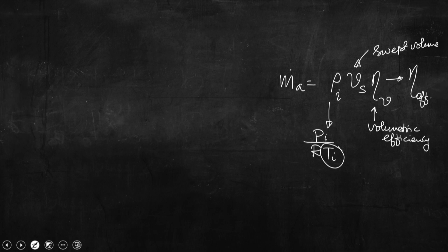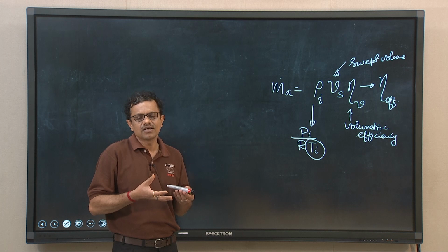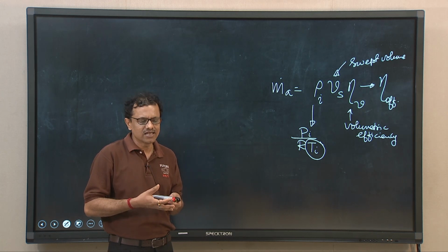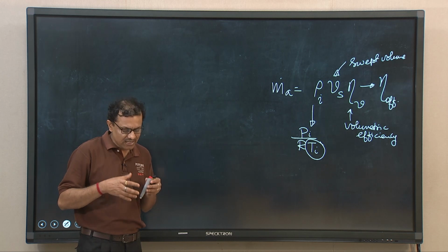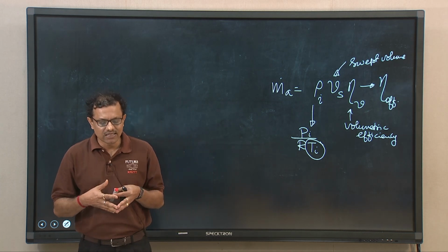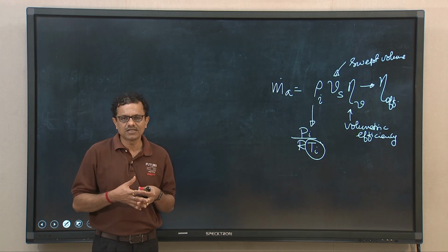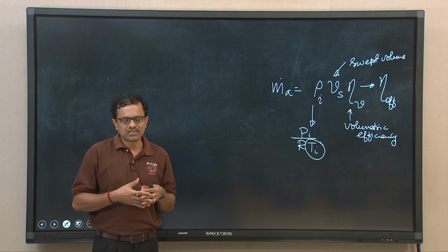The cooling water temperature and ambient air temperature sensors should always be functional, but as I said, there might be a situation when a temperature sensor will not function properly. In such a case, adequate preventive measures will be taken by the ECU or engine management system, and that alternative arrangement is replacement of default values of the faulty signal of the temperature sensor. Typically, temperature sensors are in the intake manifold and in the cooling water jacket.